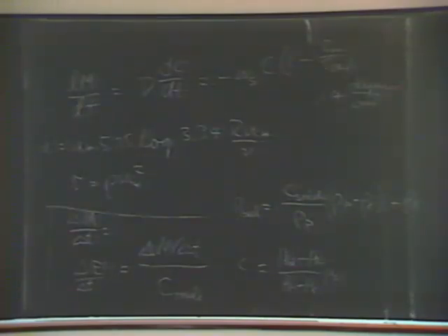In the previous problem set, there was a question asking for a calculation of the bulk density, if I recall, from moisture content determination. Most everybody got the moisture part right, but when you evaporate moisture from a sediment sample, you leave the salt in the sediment. So the density of the solids isn't 2.65, including the salt. You have to add the mass of the salt left to the volume of the sediment, and you can calculate that roughly from the difference between the density of the salt water and the density of fresh water.